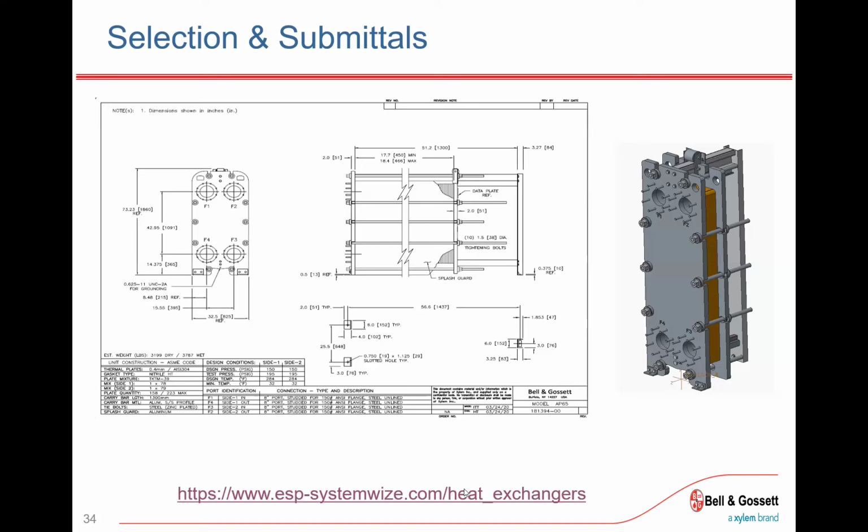But yeah, it reminds me of single wall heat exchangers for indirects. You'll see a lot of indirects out there, all single wall. Now, depending on the state, it's different codes. Like in Massachusetts, they've got their own plumbing code here, and so with single wall, as long as you have a non-toxic product on the other side, there really isn't any restriction on it. Now, other states that have adopted some of the newer plumbing codes that don't have their own, there are some limitations on pressures. I think that you can use a single wall heat exchanger.